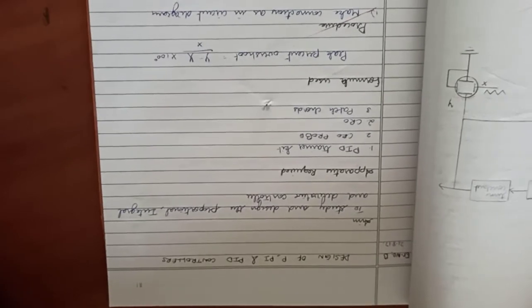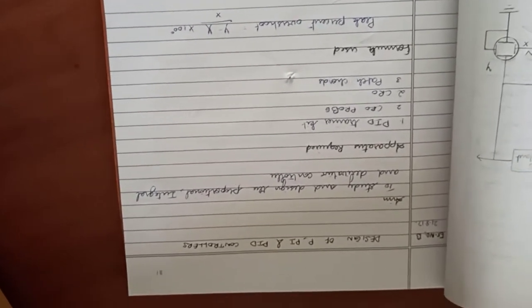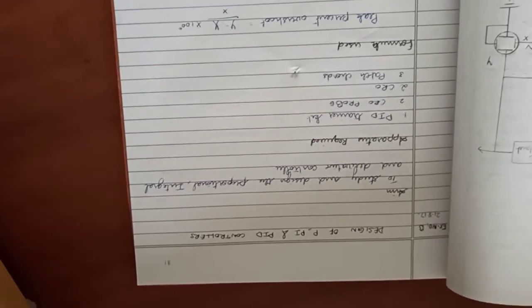We are going to realize this with the help of a kit. Generally, in the proportional controller, by adjusting the gain, the speed of response increases, but it will not contribute much to the stability of the system. When we change the integral gain Ki, it will decrease the speed of response, but it will still increase the stability of the system. When we use differential gain, it will increase the speed of response as well as the stability of the system. So it is better to go for a PID controller rather than P or PI controllers. It will systematically reduce the steady state error as well as maintain the peak overshoot value.